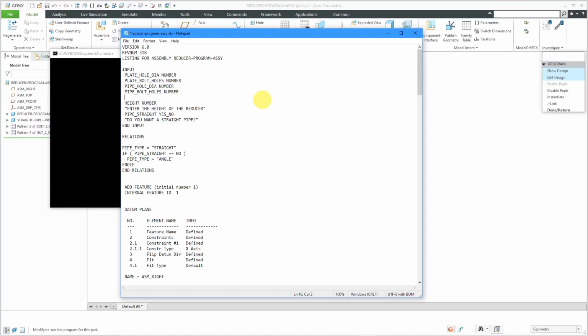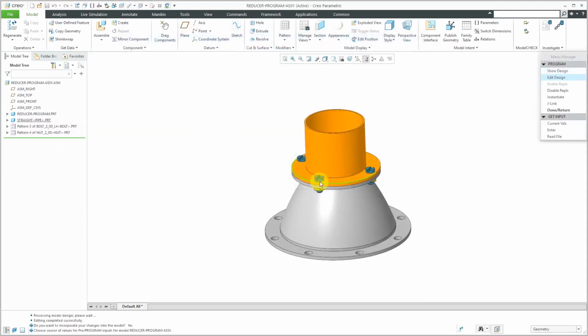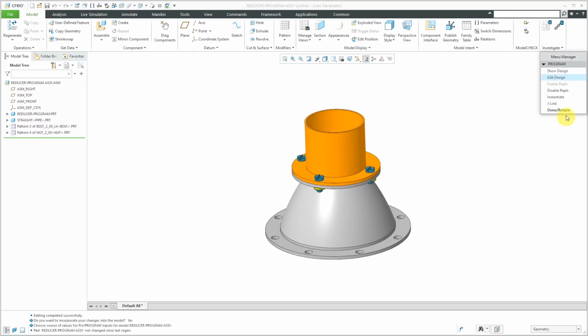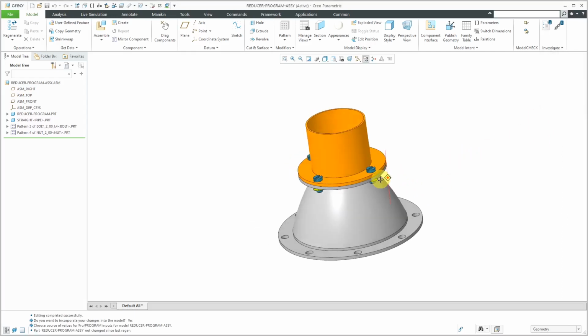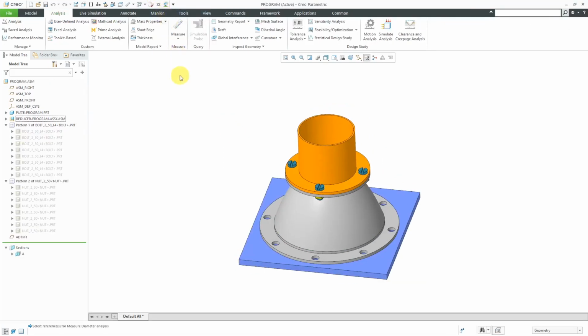We want it to receive the bolt name and the nut name from the higher level, and let me specify that these are string variables. That is good. Let's save out of here and then exit. Yes, we want to incorporate, and I'm just going to hit current values in here because, again, all I've done is say that this is supposed to receive those different parameters. I haven't sent them from the higher level assembly yet.